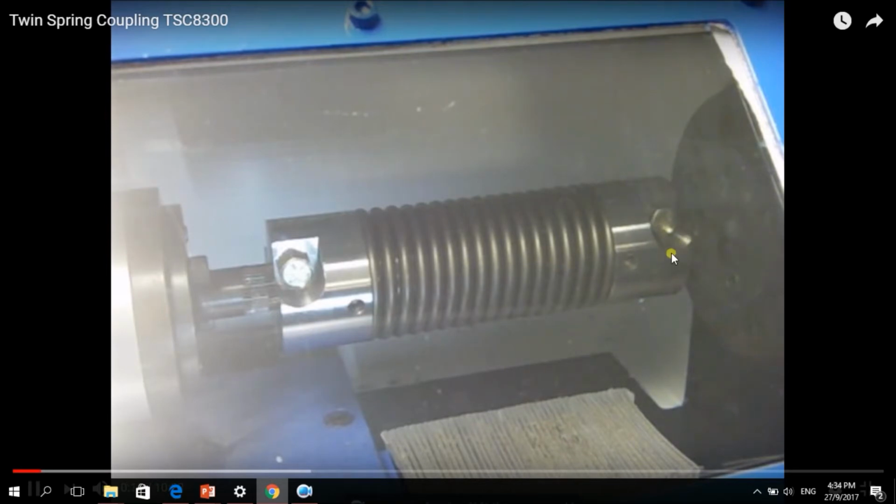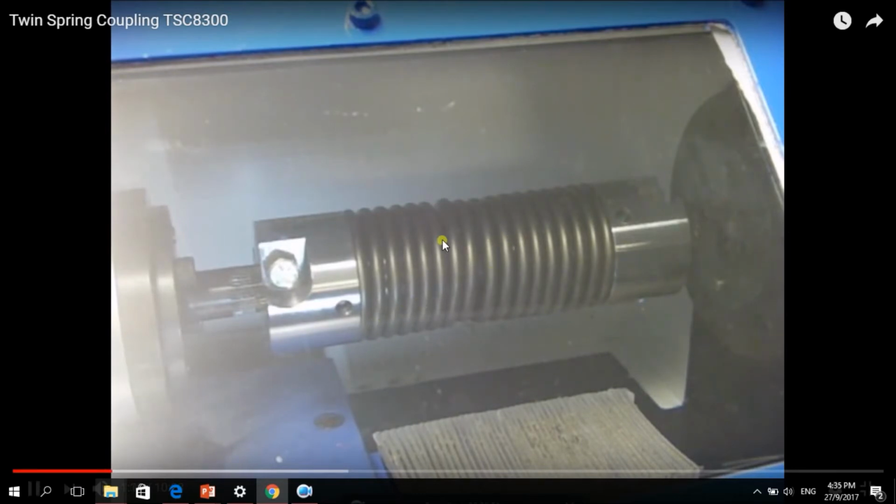This part is turning. The angle is now bigger and bigger. Okay, I'm going to say what torque it's at. 350. And until a point, you can see there's some deformation here.